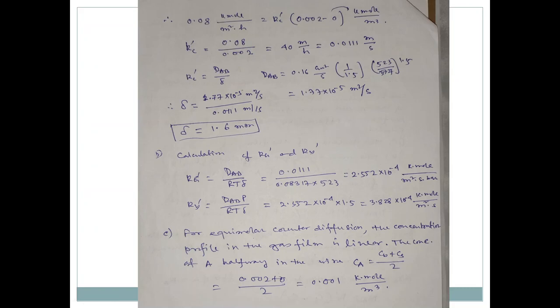Okay, but you should consider, these are the typical values of boundary layer thickness. Just 1 millimeter, 2 centimeter, 1.5 millimeter, 2 millimeter. This is the range. That is a very important parameter. You should understand, calculating this is very small, and theoretical visualization of this boundary is very difficult. Now, if you know this one, kg equals dAB by RT delta.